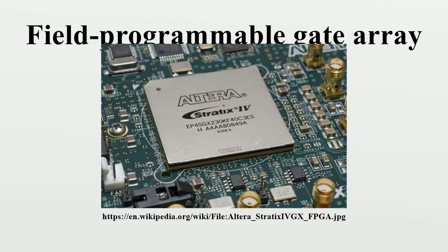Applications. Technically speaking, an FPGA can be used to solve any problem which is computable. This is trivially proven by the fact FPGA can be used to implement a soft microprocessor, such as the Xilinx MicroBlaze or Altera Nios II. Their advantage lies in that they are sometimes significantly faster for some applications due to their parallel nature and optimality in terms of the number of gates used for a certain process.